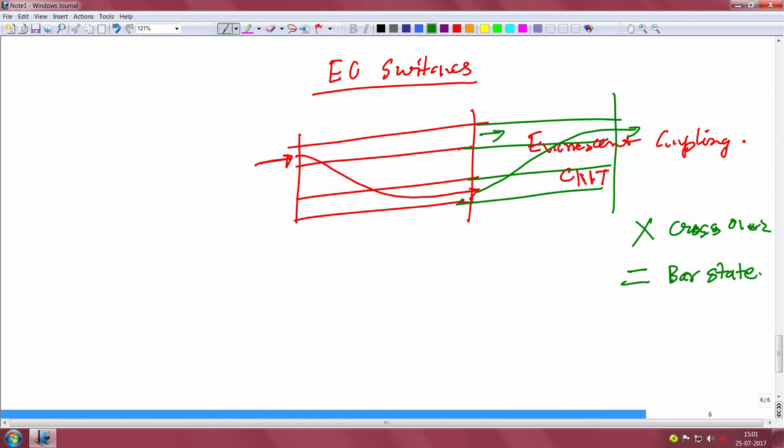But the length of the device cannot be changed easily once you fabricate, so you do not have any control on the configuration. So, we can think of a possibility where you apply voltages or use the electro-optic effect, so that this function could be realized. The requirement here is we should change the refractive index delta n such that within half the length of this device the power is exchanged to the other port, and in the remaining half the light goes back to the first port.